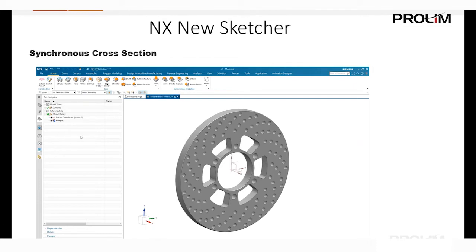Now that we've seen how it handles curves and imported geometry, let's go ahead and look at this synchronous cross-section. Synchronous cross-section allows me to take in geometry, a solid geometry, and be able to create a cross section with it. And that cross section would be put into Sketcher, the new Sketcher tool, and you can utilize that Sketcher to change your solid.